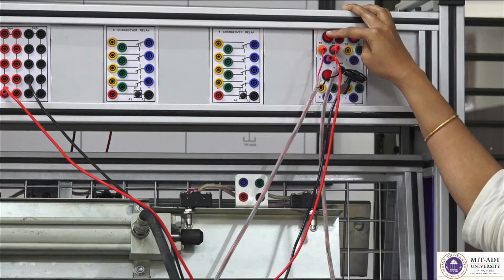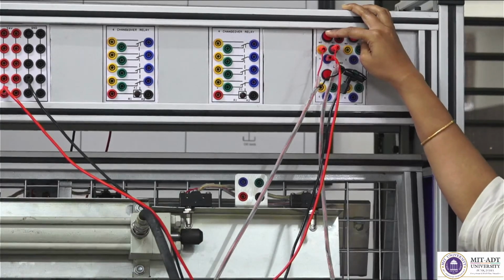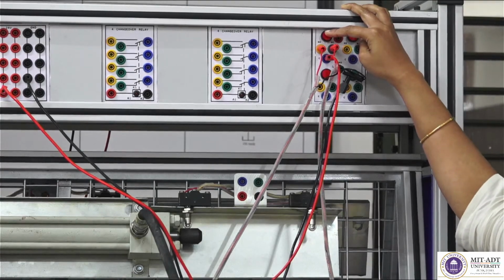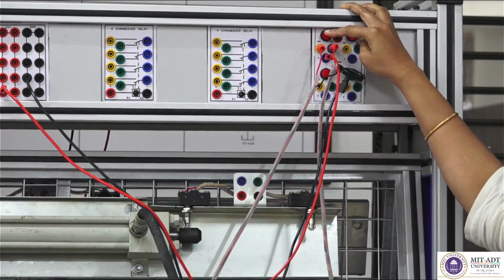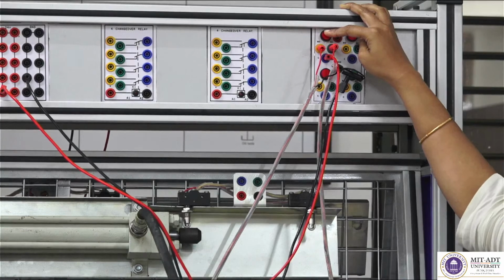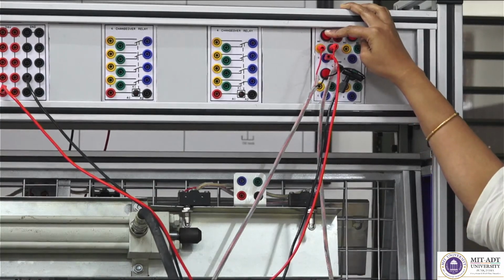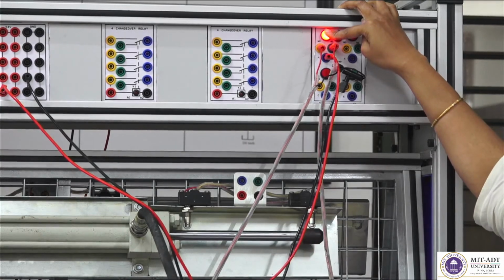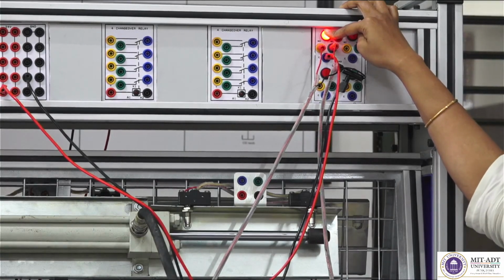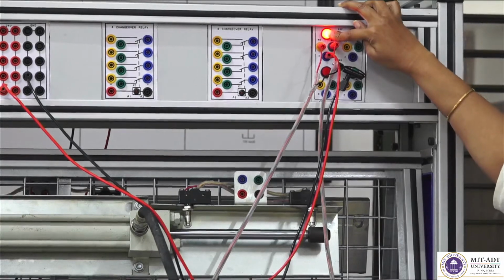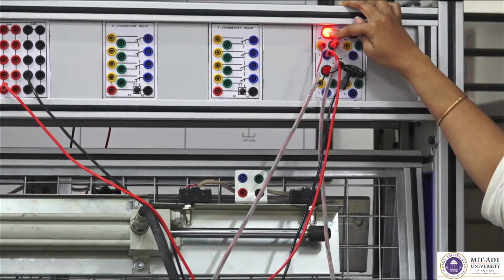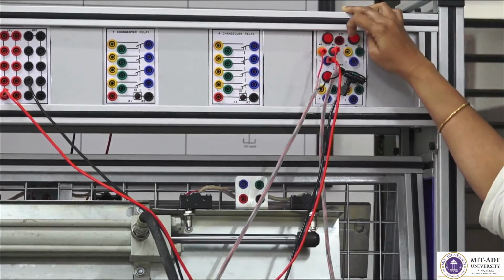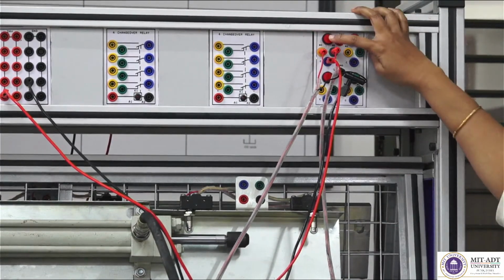So here you have seen how we have moved from lever operated DCV towards both side solenoid DCV. To the both side solenoid DCV I have given a normal 24 volt supply and ground. Then I have moved on towards relay, and now I am using this button, which is a non-latchable push button. If I keep pressing and holding this button, it will continue the motion. If I leave it, it will move back towards the original position.